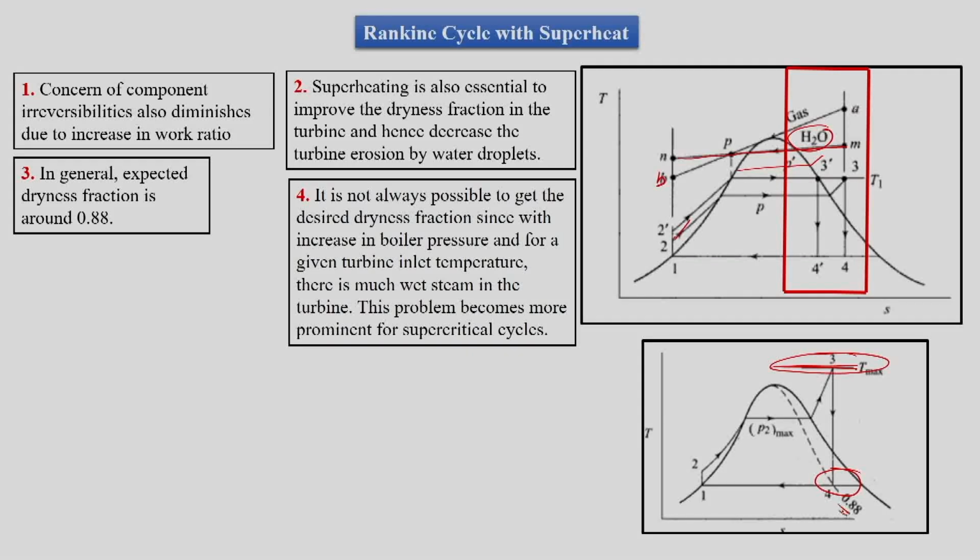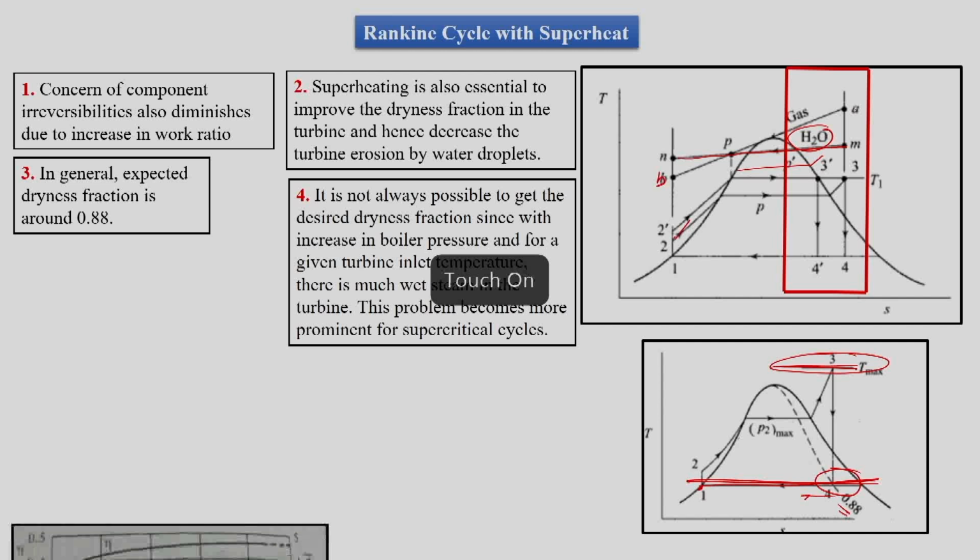We cannot go below 88%. Further, there is a limit for this line itself, that we know that we are using natural resources for cooling in the condenser. So this pressure is the corresponding saturation pressure for the atmospheric temperature of those natural resources. So this is how our Rankine cycle gets constrained from different facts.